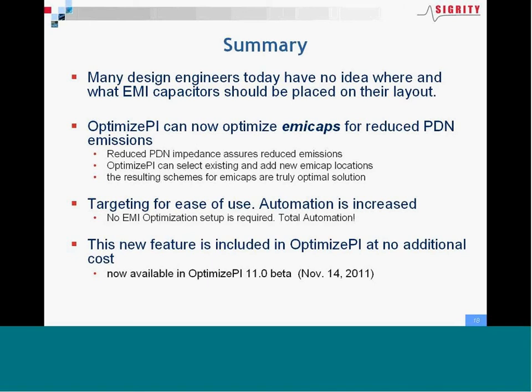And if you look at parallel planes and power delivery networks, that's very, very high in frequency. Where the simulations would tend to break down would first be where your signal integrity analysis would break down, and that would be in maybe 20 gigahertz range for via models and things like that. So if you're going to 10 gigahertz, there should be absolutely no issues with the Sigrity simulations for emissions. If you're going to 10 gigahertz, you may end up getting more cable radiation and radiation from heat sinks and things like that you're going to want to consider with a 3D solver.